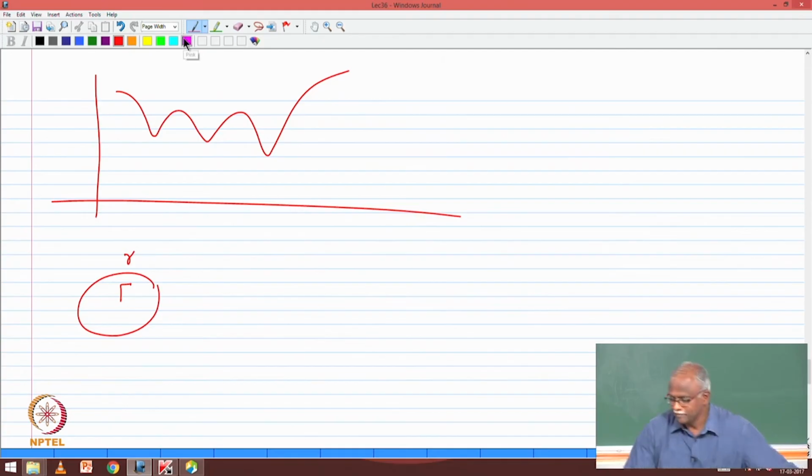So in fact, a Rayleigh fading channel capacity, what is the capacity? High now, low now, high now, low now. That's the channel that you have. Now the problem statement is, get me the maximum capacity out of this channel. That's when we start to say, hey, I know how Rayleigh fading fluctuates. I know Shannon's capacity theorem, and then I say, now put these two together. Oh, now maximizing capacity in a wireless channel is not at all trivial. It's going to be something very dynamic. I must know how to work with this channel.